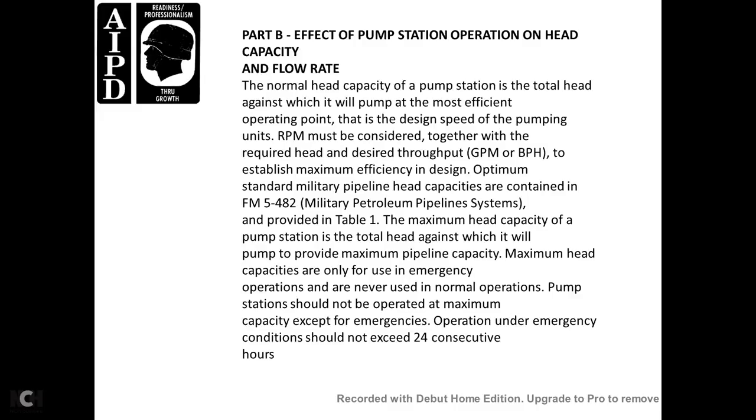Maximum head capacity is only used for emergency operation, not over the normal operation of the pump station. The station should not be operated at minimum capacity except for emergency operation. Under emergency conditions, it should not exceed 24 consecutive hours.